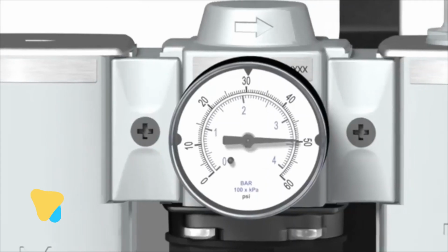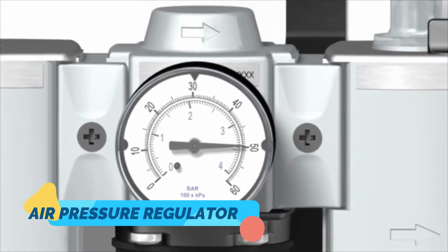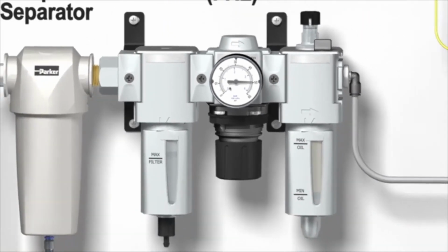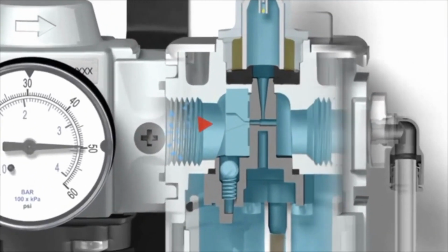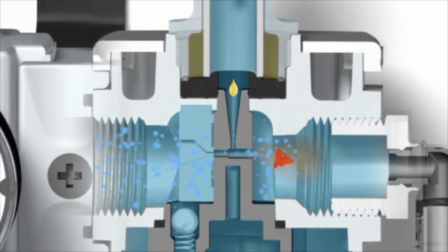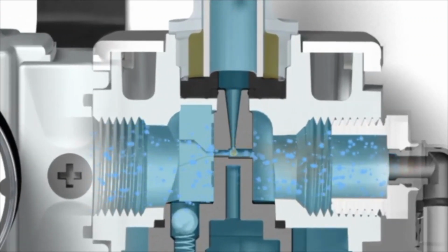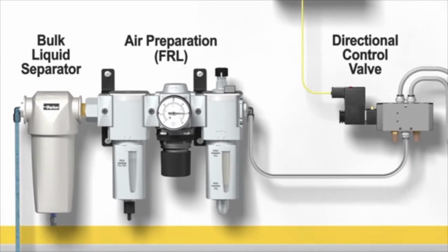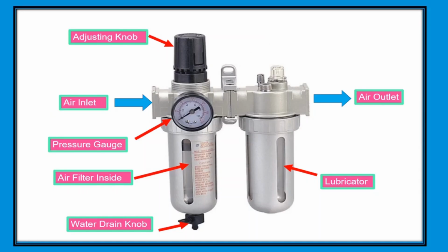Number 6. Air pressure regulators reduce supply pressure to the level required for efficient operation of pneumatic equipment. They reduce a supply or inlet pressure to a lower outlet pressure and work to maintain this outlet pressure despite fluctuations in the inlet pressure. The reduction of inlet pressure to a lower outlet pressure is the key characteristic of a pressure regulator. When choosing a pressure regulator, many important considerations must be taken into account. These include operating pressure ranges for inlet and outlet.